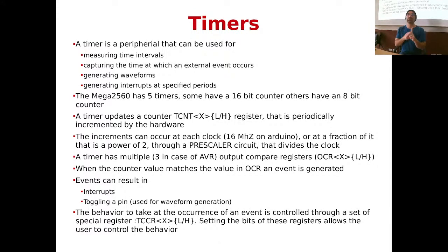And also you don't want to write, we'll see it later, an interrupt routine that stops the timer when you hear the echo, because this will incur the latency of the interrupt. When the interrupt comes, the processor says, oh, what was I doing? Then you have to save the state, go to the interrupt table, read the interrupt vector, jump to it, start executing the interrupt routine, and already many cycles have passed.